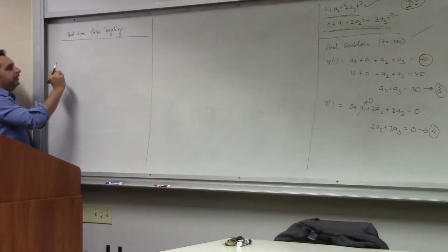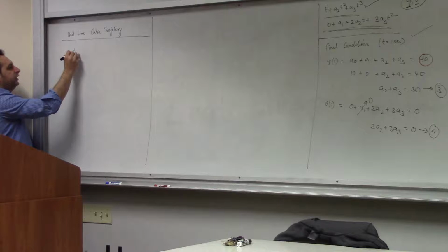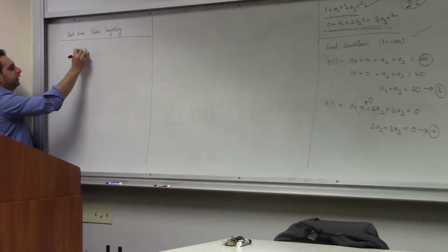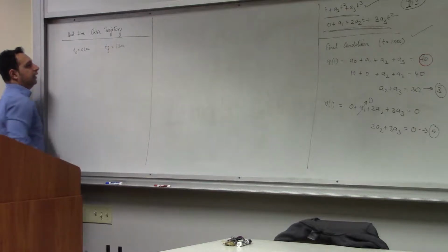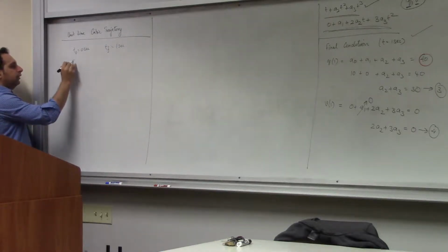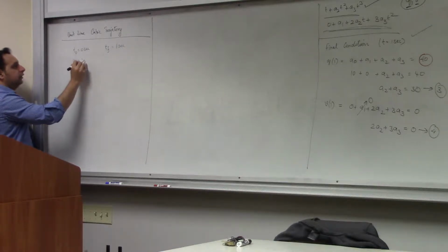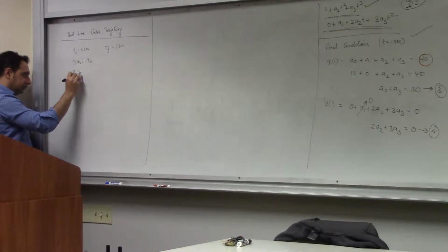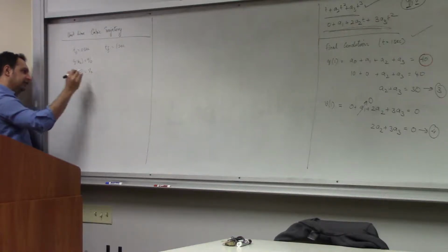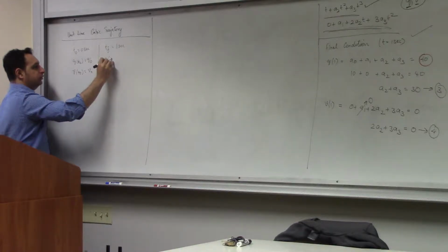Let's do the unit time trajectory. In this case, unit time means you're starting from t0 equal to 0 seconds, and you stop at tf equal to 1 second. Okay? q of t0 is q naught. Same thing, v of t0 is v naught. These can be anything. You can come up with any values that you want to.